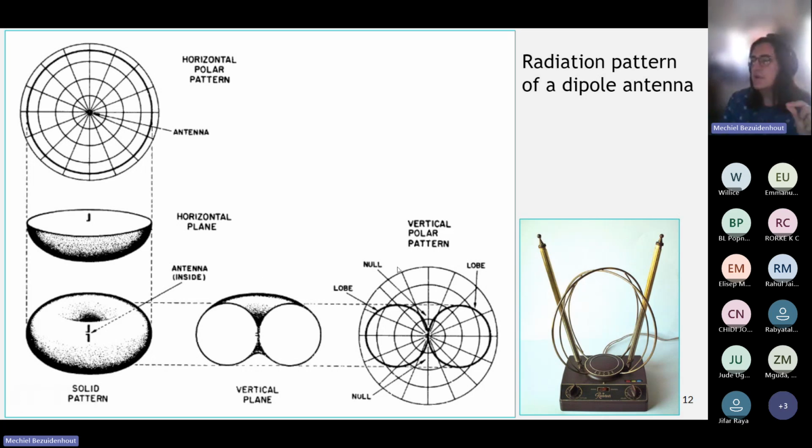So a very important principle with these radiation patterns is that the pattern broadly reflects the symmetry of the antenna. So here we have an antenna that's radially symmetrical, right? So it's the same in all azimuthal directions, meaning that the radiation pattern will also reflect that radial symmetry.